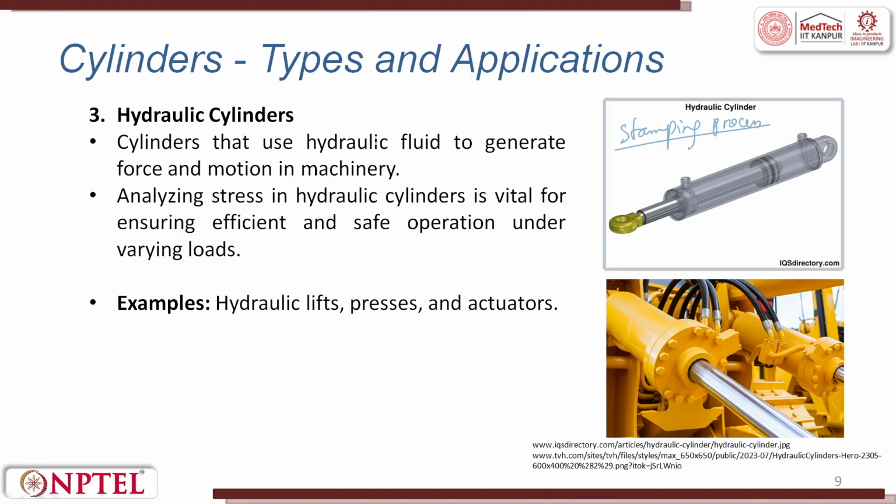So, shearing must have much heavier loads. So, hydraulics are used. The hydraulics move vertically up and down. These cylinders use hydraulic fluid to generate force and motion in machinery. Inside the cylinder you will have liquid which is pressurized. As and when you compress, the liquid is pressurized. Once it is compressed, the pressure is exerted on the wall.